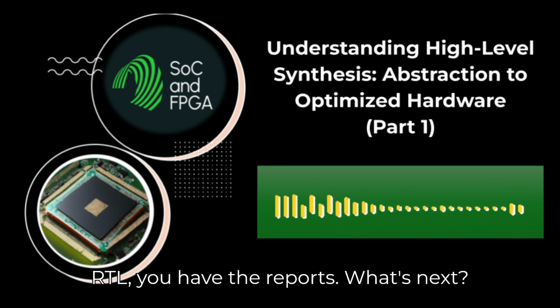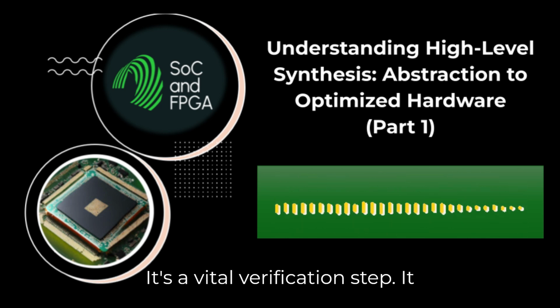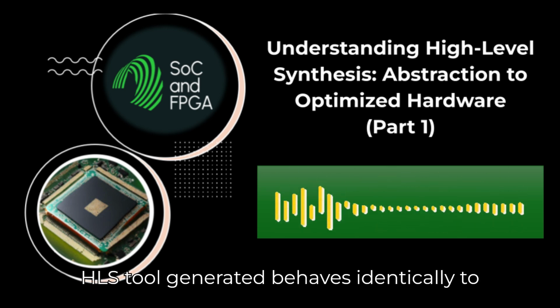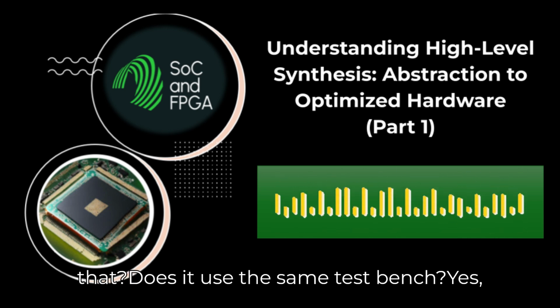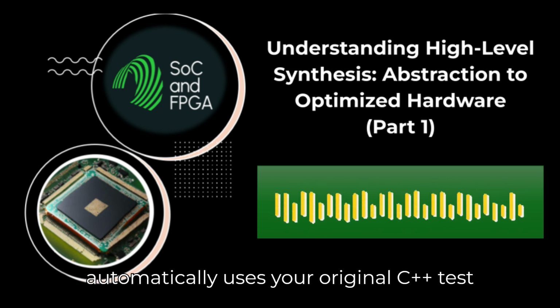Okay, you have the RTL, you have the reports. What's next? C/RTL co-simulation. Sounds important. It's a vital verification step. It essentially checks if the hardware the HLS tool generated behaves identically to your original C++ code. How does it do that? Does it use the same test bench? Yes, that's the beauty of it. The HLS tool automatically uses your original C++ test bench.